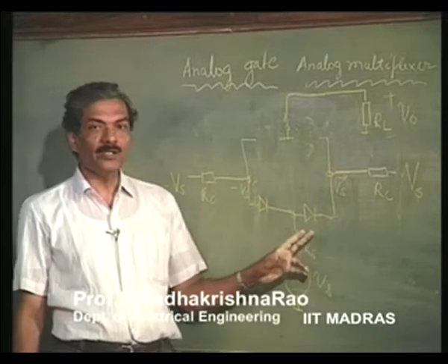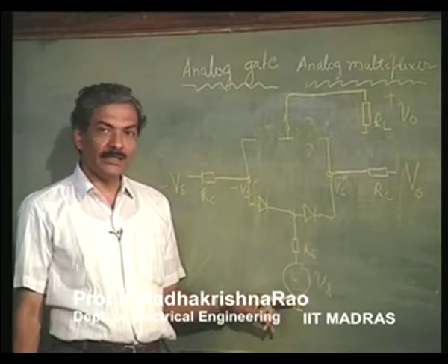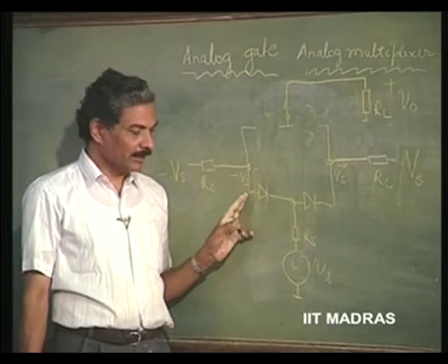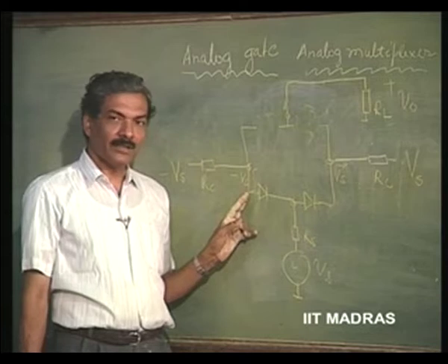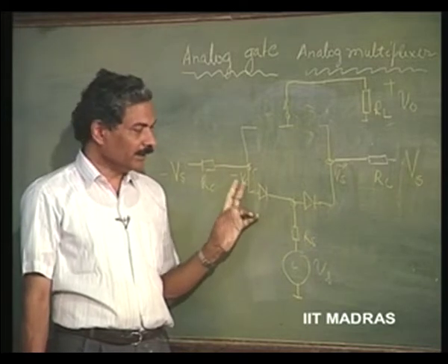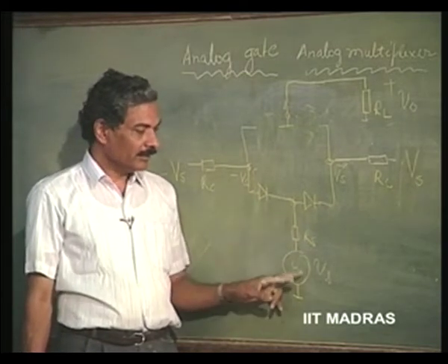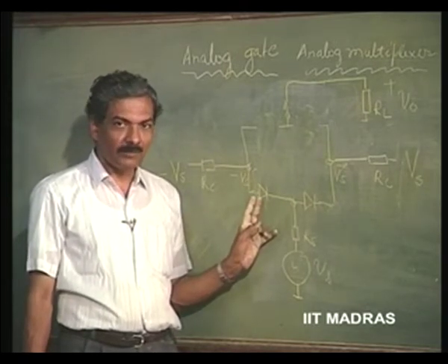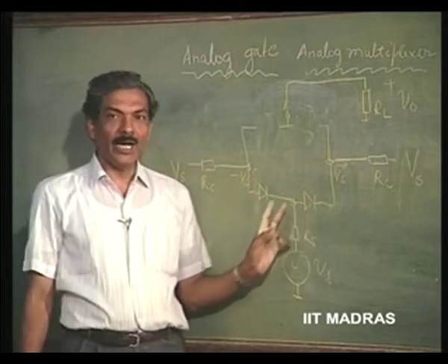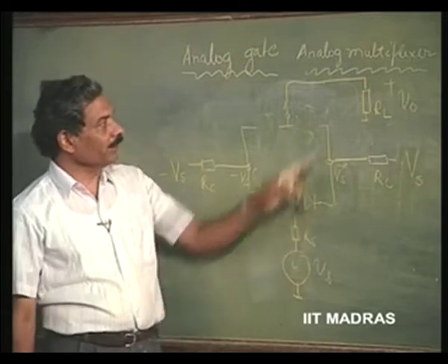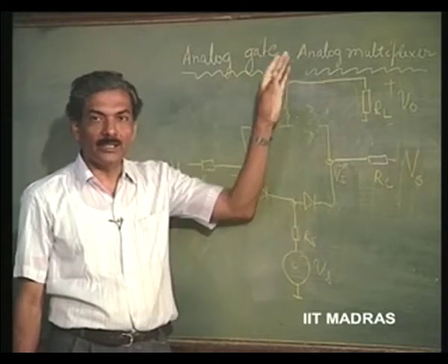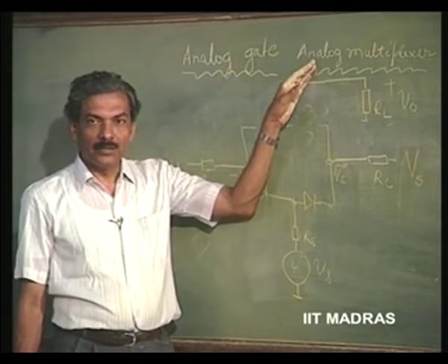Only thing is these diodes might conduct if vs exceeds the magnitude of this capital Vs. If this DC voltage is exceeded, then these might conduct; then also no harm occurs, but we would like to have this also acting as an open circuit, so that from here to here you have two open circuits in series. So, it is totally isolated from this load.